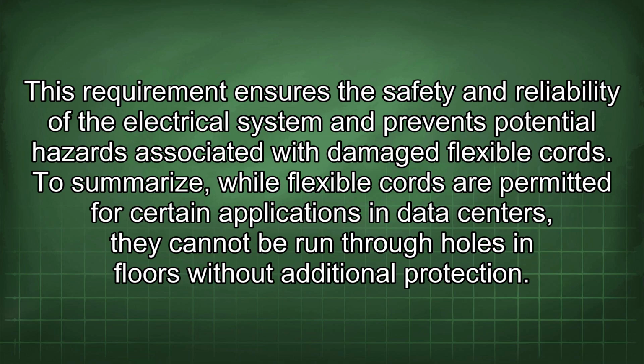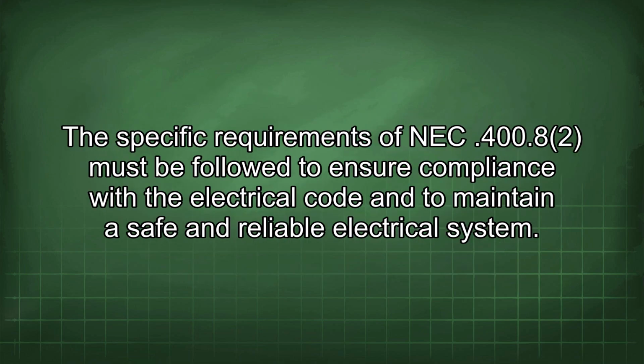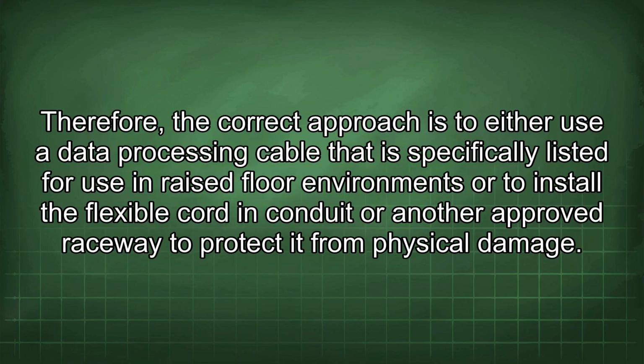To summarize, while flexible cords are permitted for certain applications in data centers, they cannot be run through holes in floors without additional protection. The specific requirements of NEC 400.8 must be followed to ensure compliance with the electrical code and to maintain a safe and reliable electrical system. Therefore, the correct approach is to either use a data processing cable that is specifically listed for use in raised floor environments or to install the flexible cord in conduit or another approved raceway to protect it from physical damage.